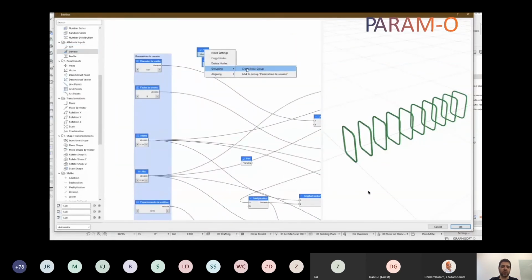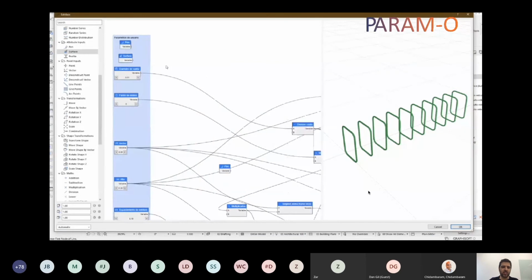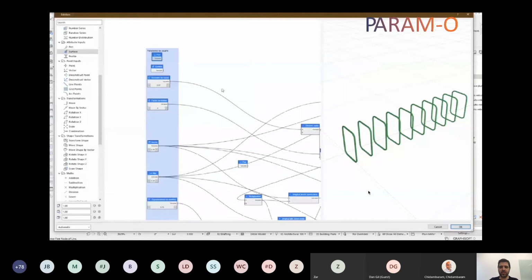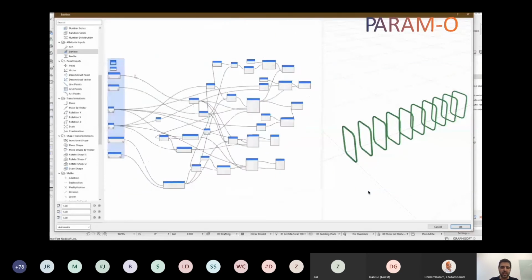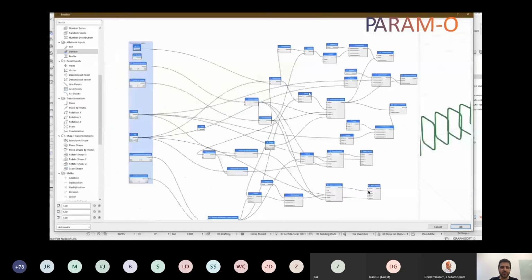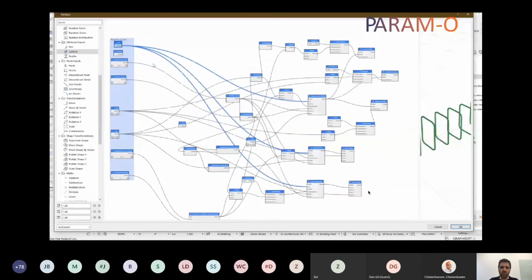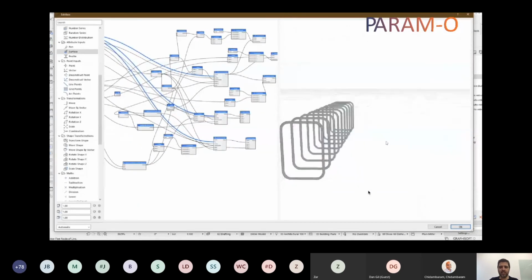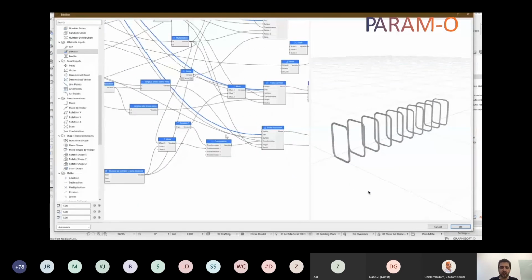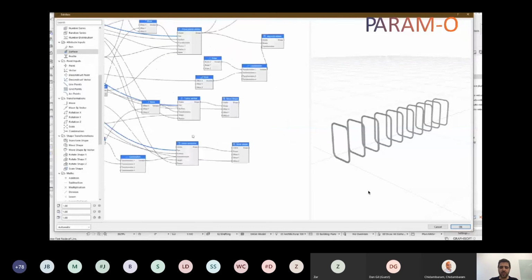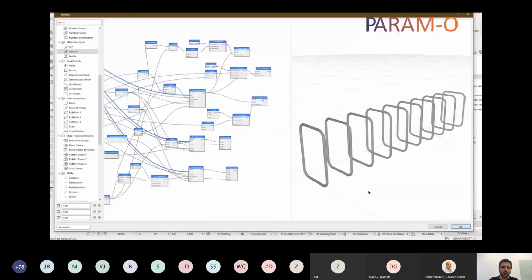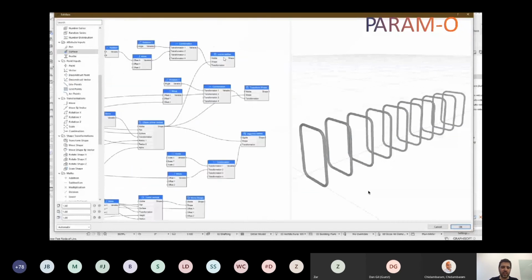So now they decided, okay, we also want to change the pen and we also want to change the surface. So we will choose what kind of surface we want to use for these rebars, and then you connect these 2 nodes to the relevant elements that should be represented with that pen or with that surface. So you see that once they are connected, that gray surface that was chosen by the user is the one that becomes connected to the element. So we can then double check everything.